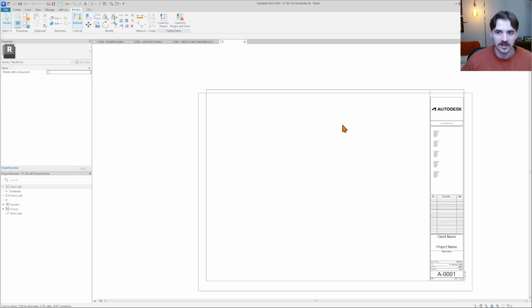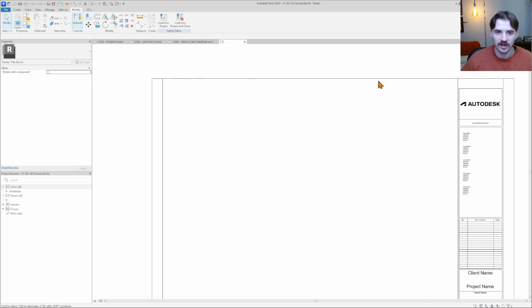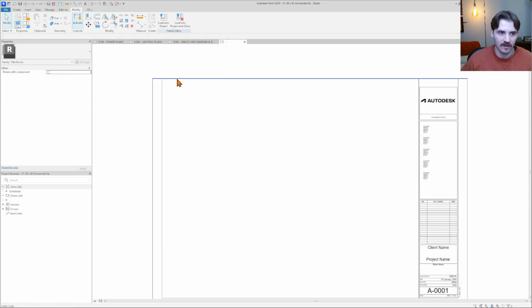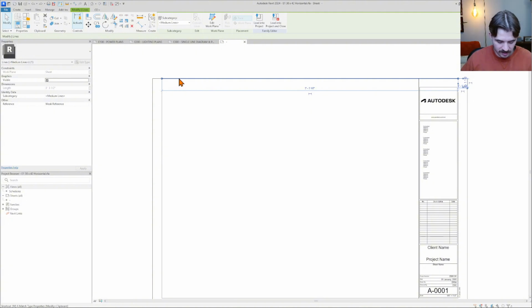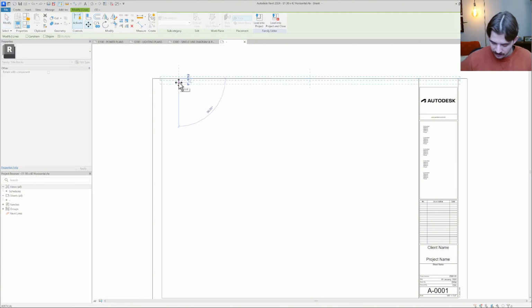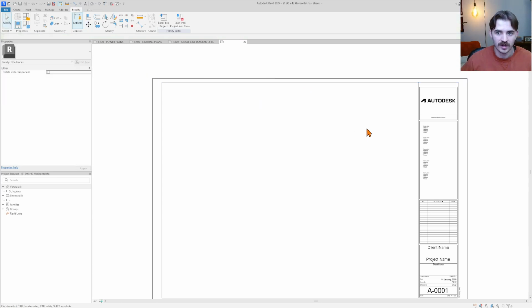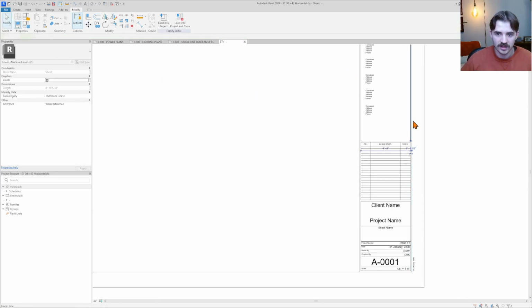And now my margin is 1/2 inch. Oh, well, I grabbed the wrong line. What happened there is I grabbed this line, the outer edge. I want to make sure I'm hitting Tab here until I get underneath that for the inner boundary. And now I'm going to do the same thing where I move 0.5 inch. There we go. Now we can do the same thing out here.